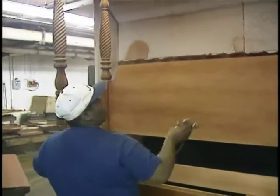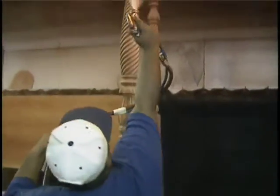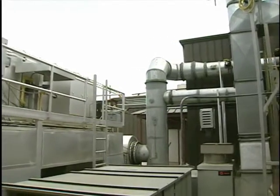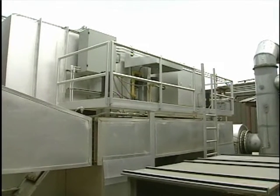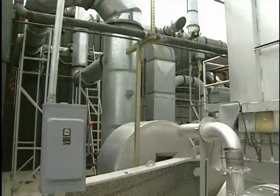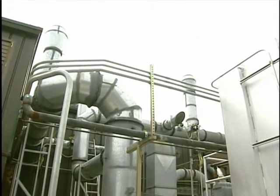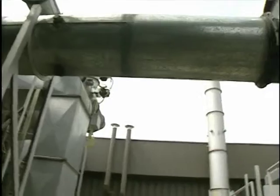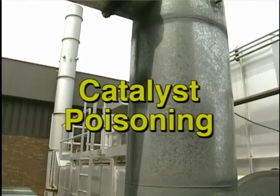Catalytic oxidizers usually cannot be used effectively on waste gas streams with high concentrations of liquid or solid particles. These particles deposit on the catalyst surface, blocking access for the organic compounds. This is termed fouling. When low concentrations of particles are present, periodically cleaning the catalyst can restore more than 90% of its activity. Certain metals can react or alloy with the catalyst, permanently deactivating it. This is referred to as catalyst poisoning.